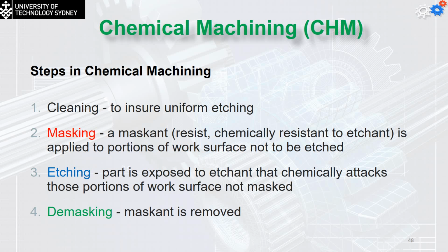So it's the same process, but instead of paint we use the etchant material, and instead of masking using paper, we use something which is going to resist this material. Spray it, it starts the etching, remove the mask, and you have the cutting appear.